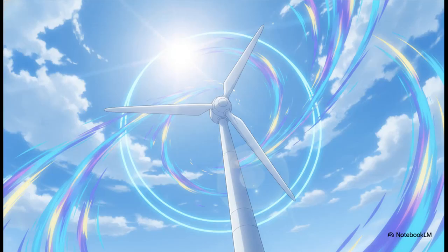Okay. Everything we've talked about so far is governed by one beautiful mathematical formula, the power in the wind equation. Power equals 1/2 the air density times pi r squared times the wind velocity cubed. So what does this actually mean for us? Well, it means power output increases exponentially. If the wind blows just a tiny bit faster, the power cubes. And if we make our blades longer, increasing that r for radius, the power squares.